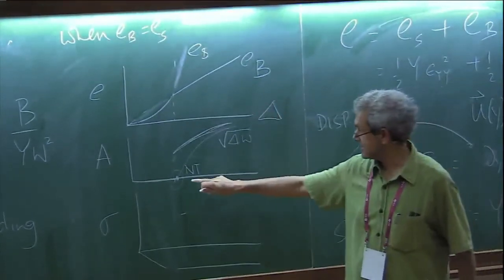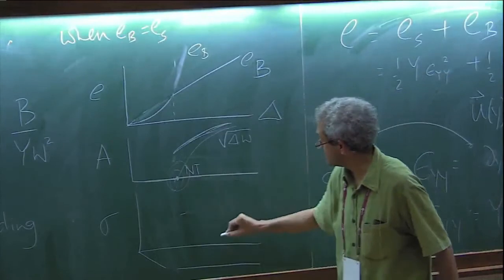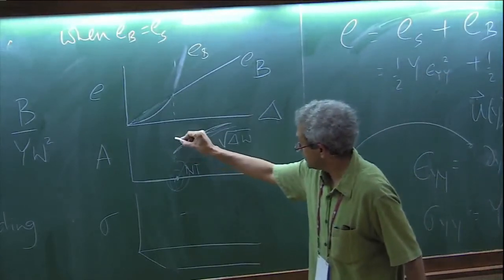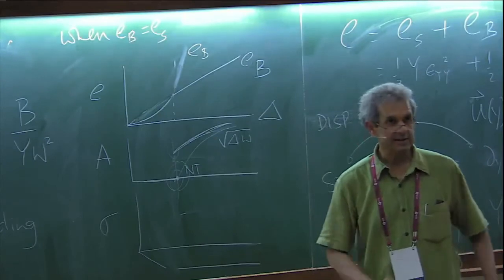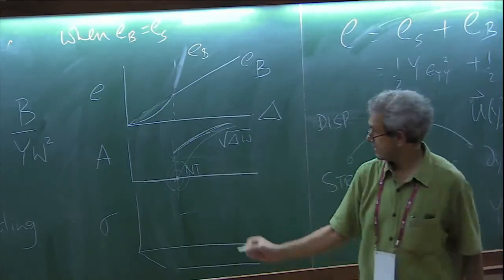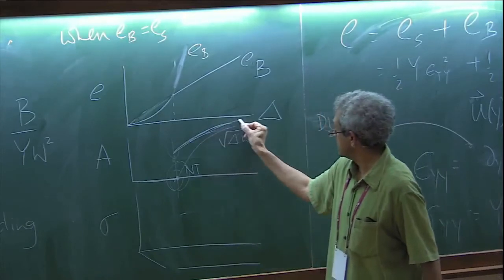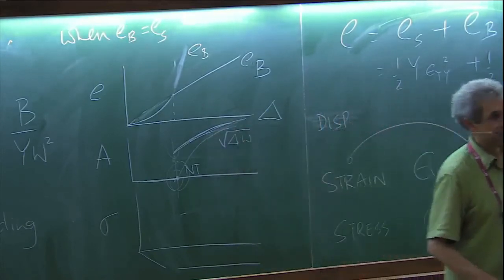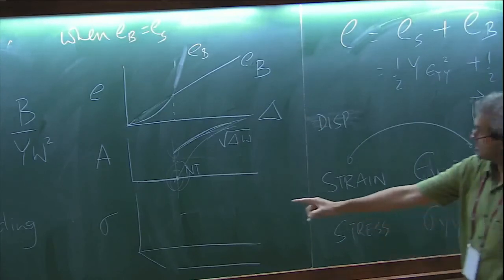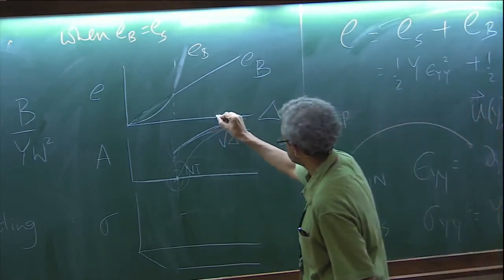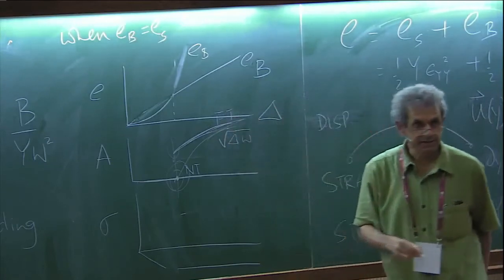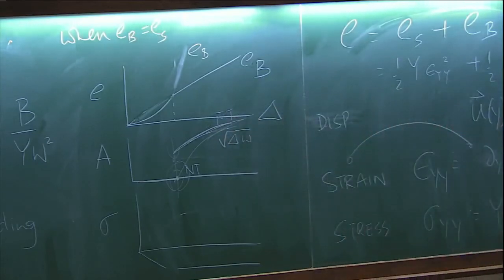It turns out that the thing that works near here and this way of doing it give exactly the same threshold. They change the character of the transition, but they match up at large values when you're very far from the transition. So this near threshold picture happens to match up with the far from threshold picture, and that's an accident in Euler buckling. And I want to tell you that it's an accident because it doesn't always do it, and we will soon hit problems in which the answers look different.